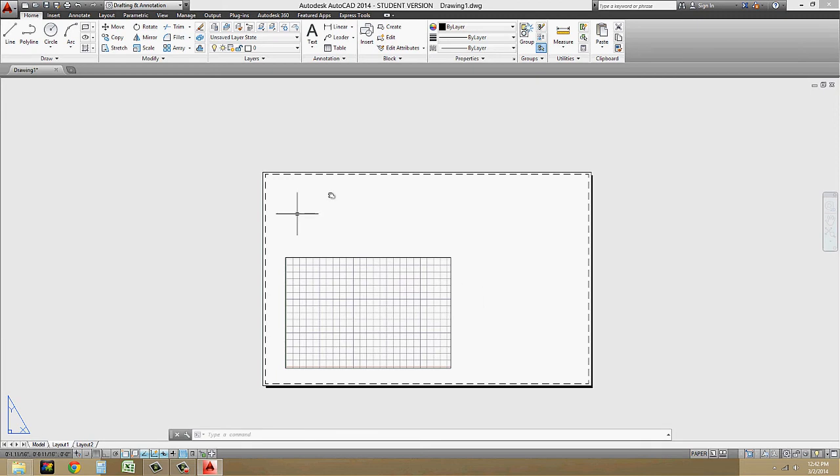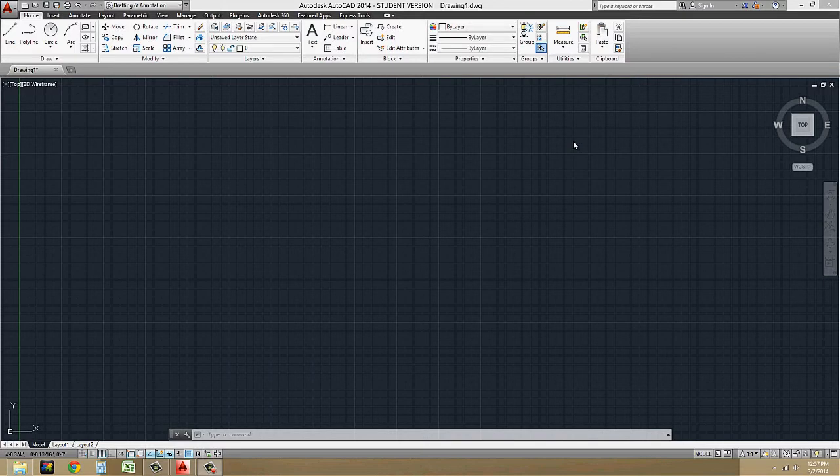Okay? A lot of people say, well, my title block is XREF'd into paper space, so if I go to XREF that into another file, why doesn't my paper space information come with? And that's the reason. Only objects in model space are XREF'd. Now what we're going to do is start to set up our sheets in paper space. These are the sheets that are going to make up our final drawing set for the rest of the semester that we're going to be working on.